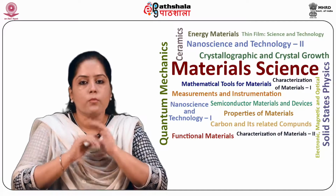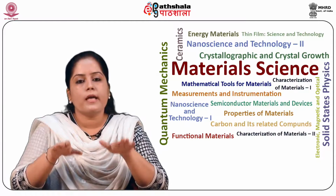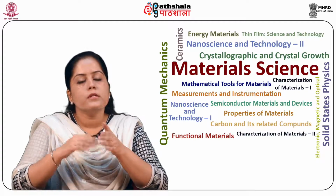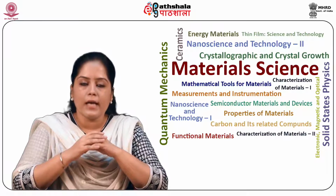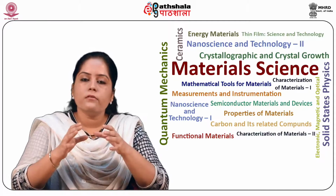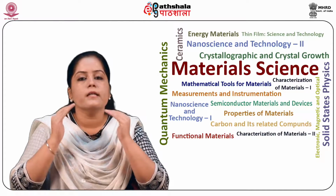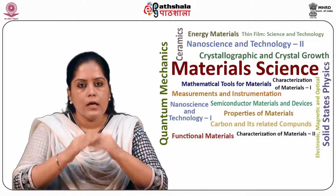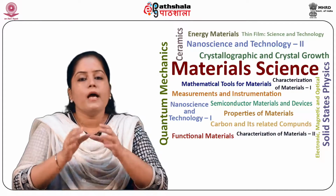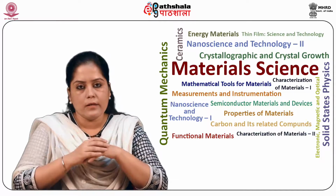The unique feature of the MODFET is the heterostructure in which the wide energy gap material is doped and carriers diffuse to the undoped narrow energy gap material where the channel is formed. So the net result of this modulation doping is that the carriers in the undoped heterointerface are spatially separated from the doped region and have extremely high mobilities because there is no impurity scattering.